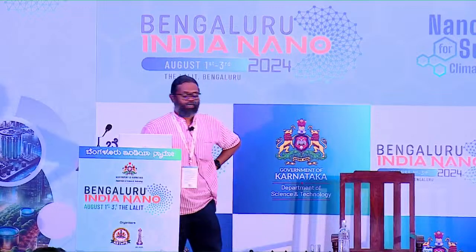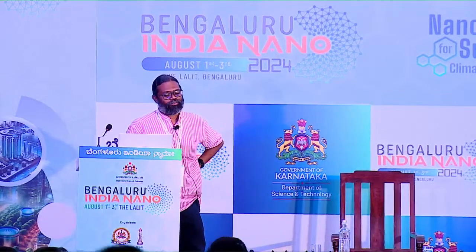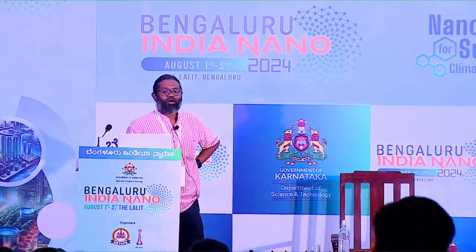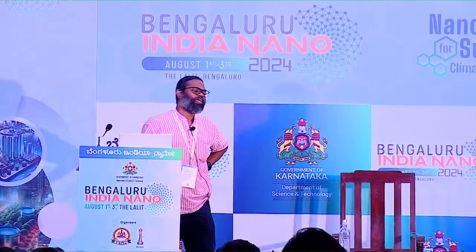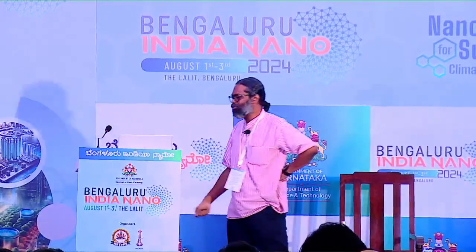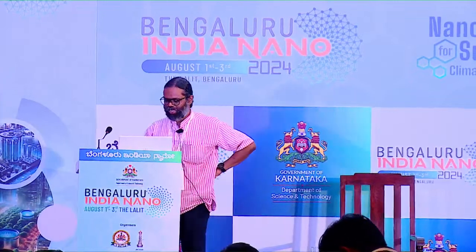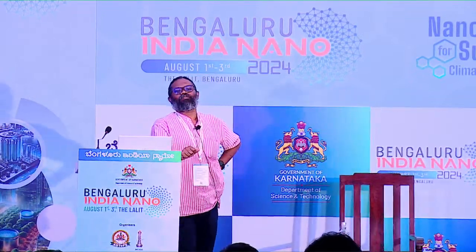And then we do a cleaning of this, and then after cleaning, you come in with oxide again, right? So it's called atomic layer deposition or physical vapor deposition of dielectric. And on top of the dielectric, you can put a polysilicon, polycrystalline silicon. Again, silicon is core here. We deposit it using chemical vapor deposition techniques, and then we use lithography.